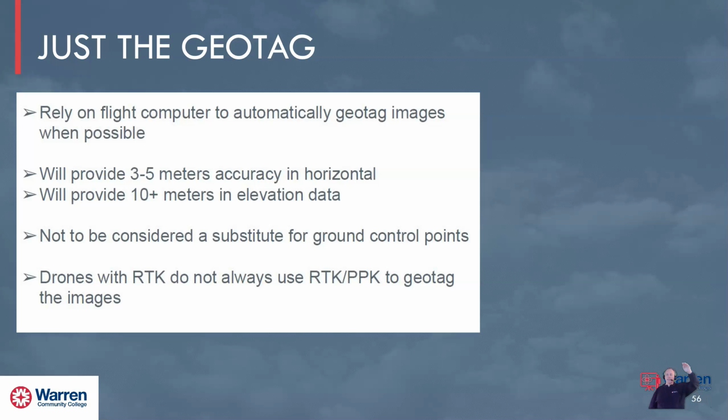It's going to estimate its elevation on how long it takes the signal to go from the satellite back, but there's going to be an accuracy here. And when you think about it, when we're talking about 2 centimeters versus 3 meters, which I can't even reach to, there's a huge amount of inaccuracy that can come with just geotagged photographs. It's not a substitute for ground control points.